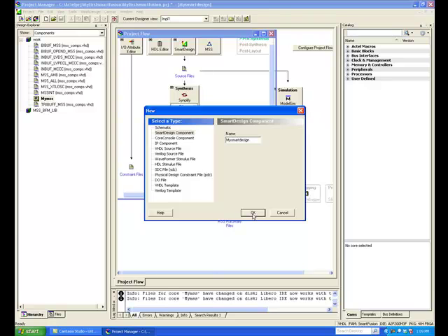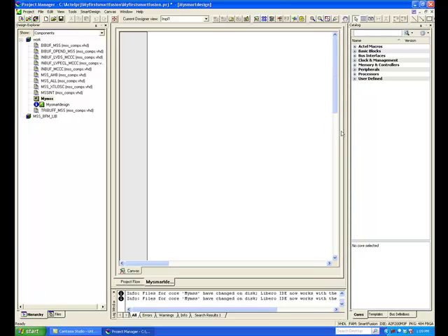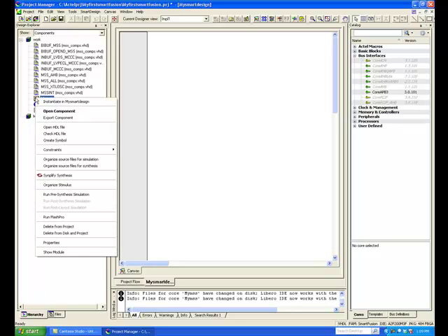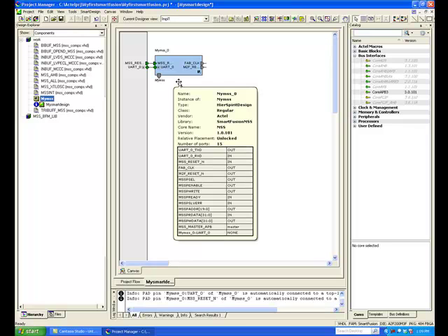Make sure that your Libero IDE catalog is visible and that you can view the names of the various IP cores. From the Design Explorer, right-click the MyMSS IP icon and select Instantiate in My Smart Design, or you can drag it onto the canvas. Note that the instantiated MyMSS component looks like any other instantiated block in Smart Design.